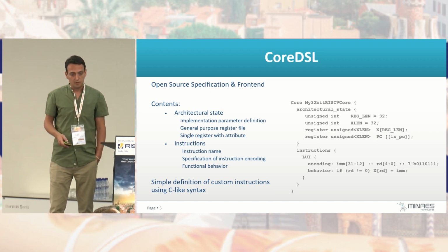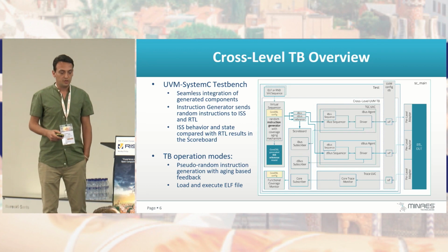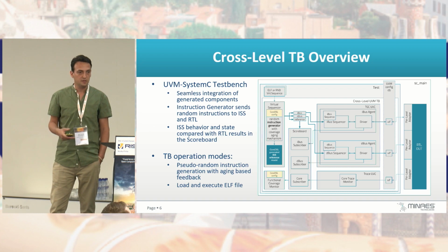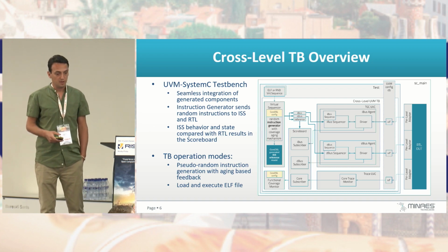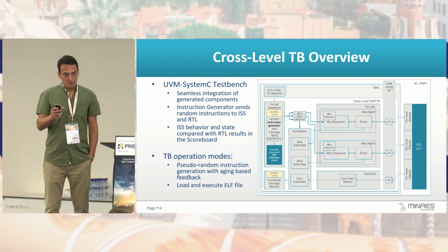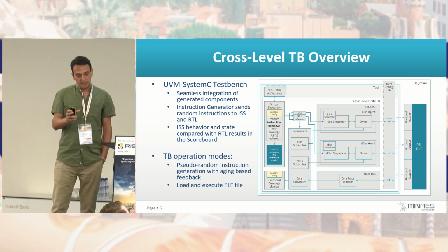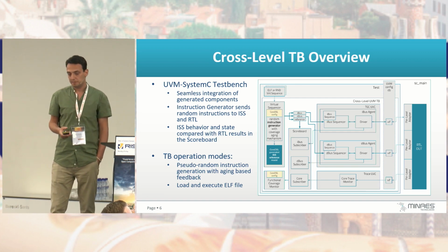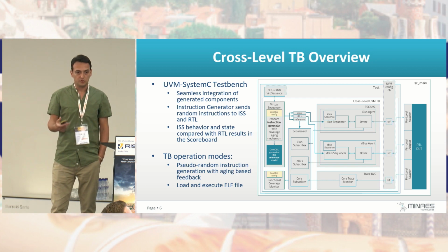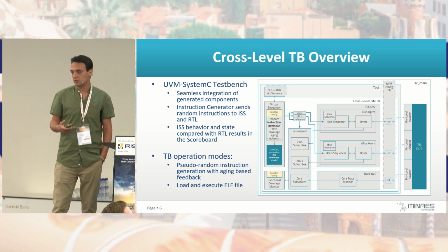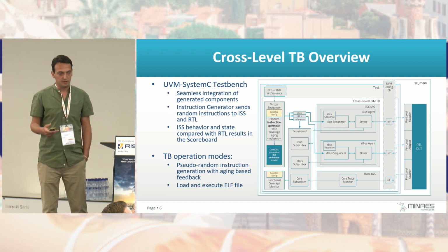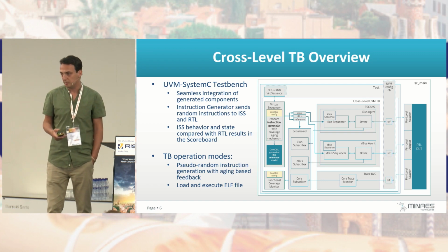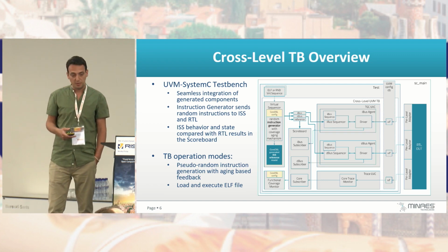So the generated components from the CoreDSL description will be seamlessly integrated into the UVM cross-level test bench. And for the setup of this test bench, we choose to use the UVM-SystemC library because it brings the strengths of both the UVM methodology and SystemC, and it significantly simplifies the integration of the ISS into the UVM environment, because both are actually implemented in C++.